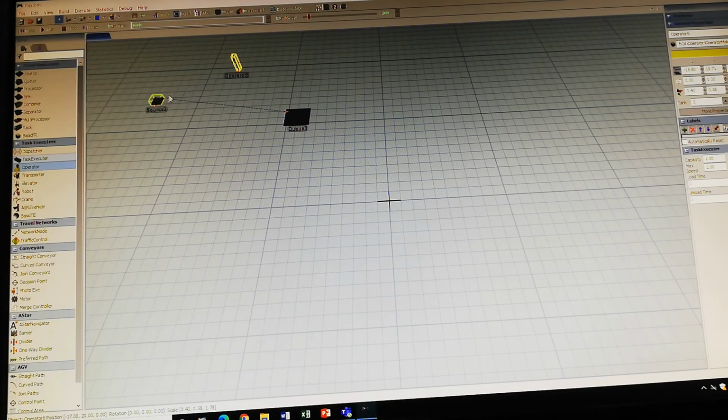In this moment, you can see that when you give one click in source, on the left, you are going to have one option that says use transport. You are going to select only this option, use transport, one click, and this is indicating that your transport, who is the operator, is going to travel to this part, choose the product, and give it to the queue.